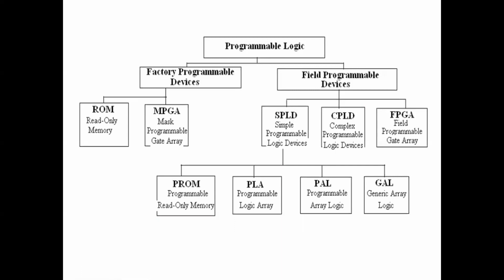So these programmable ICs are standard ICs that are available in standard configurations. And programmable ICs can be programmed to create a part of customized ICs to a specific application. These ICs contain a large number of AND and OR gates, and also flip-flops that can be configured or programmed by the user to perform that particular application.